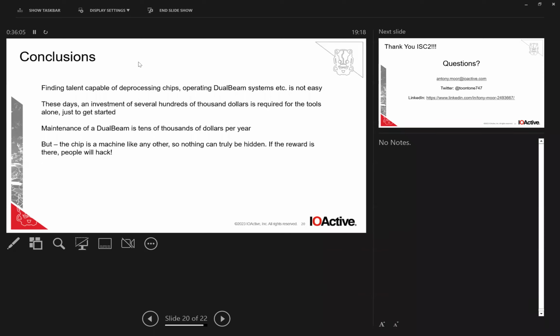If the shield is in bunches of 4 lines, 4 tracks, you can't just reroute one of them, because the signal won't match. You'll have 3 hitting the opposite end of the chip at one point, and there'll be one slightly delayed because it's had to go further. I mean, the sensitivity is incredible. So you'd have to reroute the other 3 tracks. So it's roughly timed still, but there's always some sensitivity, of course.